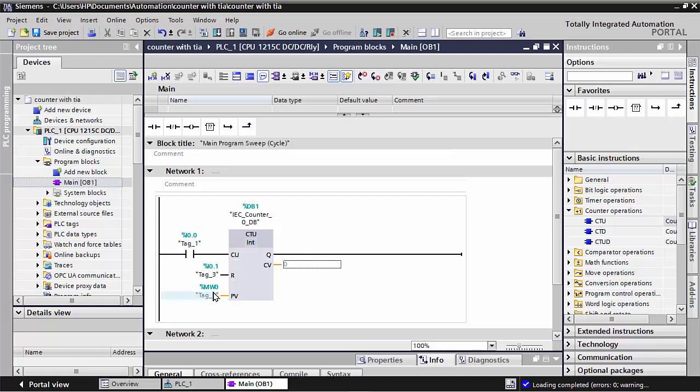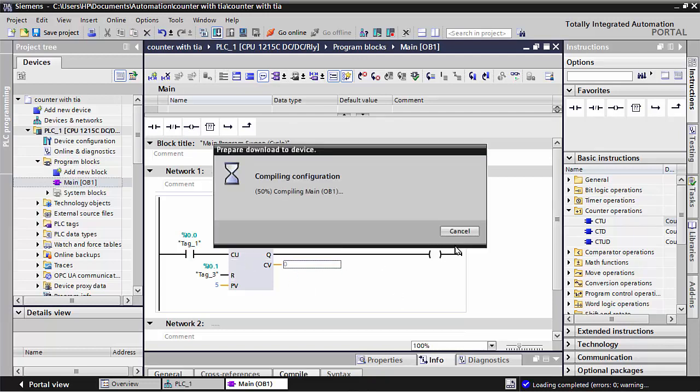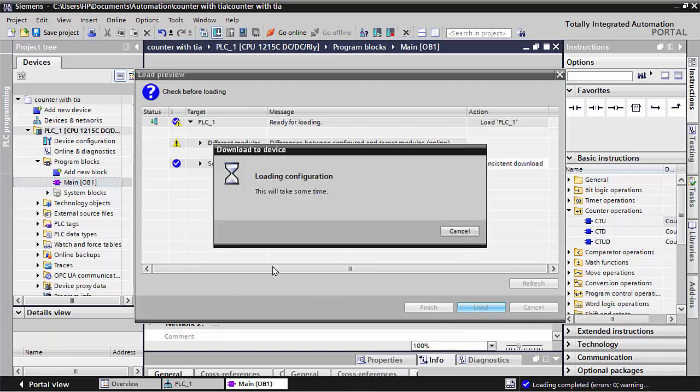Counting, you have to tell it here MW0, how much you count up to, the ceiling, because of this data register we give. Also we can give only counts here, and if you give the counts as 5, it will take the 5 counts. And also it asks what thing you would like to be on after your counts are completed, and I say here I need one output, Q0.0, and this program I will download to my PLC and then click load.